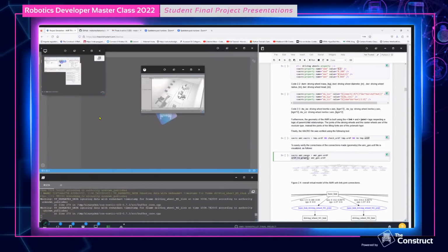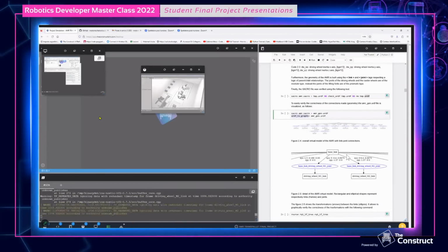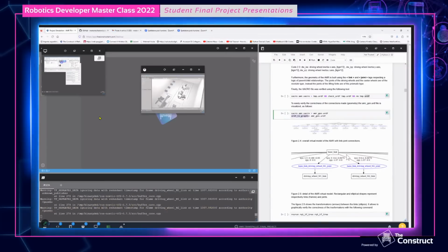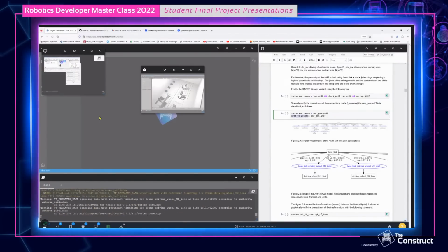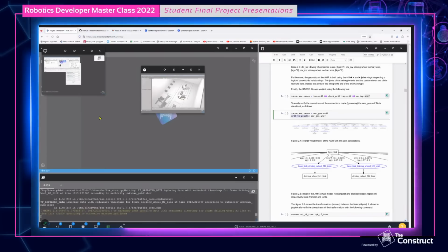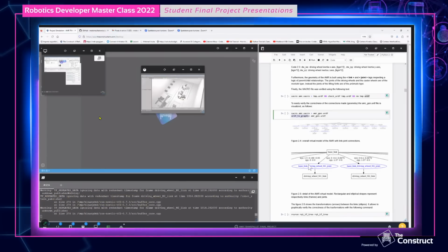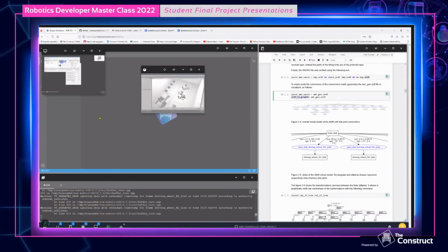This one, URDF to graphics, gives the possibility to verify graphically the correctness of the URDF, the geometry. Here the rectangular shapes are the frames, and the elliptical shapes are the joints. You know that the robot is a kinematic chain of links and joints, so this graph is properly this.